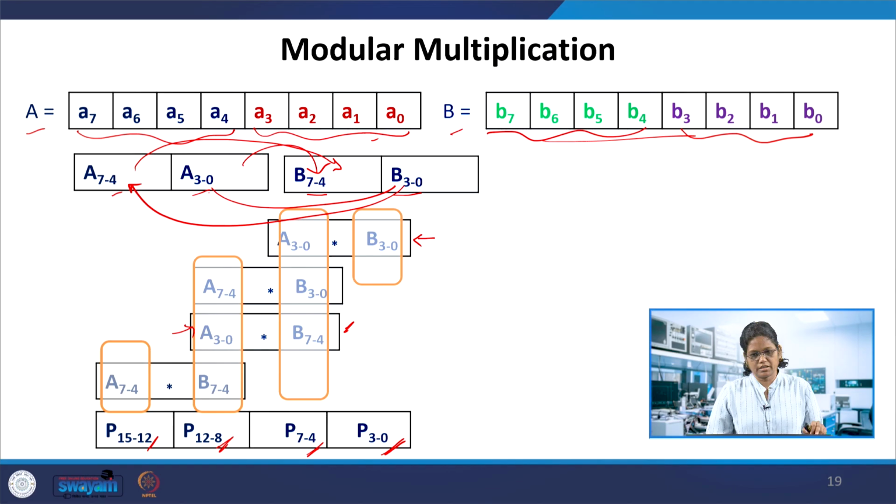With this we have seen the ripple carry adder: what is the time involved in the sum and carry generation if you have n bits, and how the worst case delay is affected due to the ripple through addition. We also saw the multipliers, the conventional and unconventional ways. If the multiplicand and multiplier are both negative, that multiplication can also be done: negate the numbers and then multiply them as such.